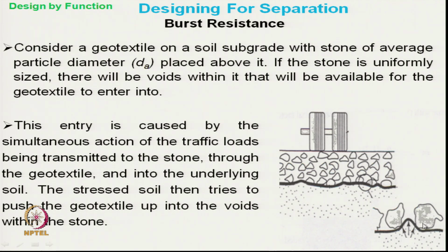This will have some bursting force. So, bursting resistance is important. If the bursting strength is low, then there will be damage in the geotextile and this separation function will not be there. So, for designing of geotextiles for separation function, we must take the bursting strength into consideration.